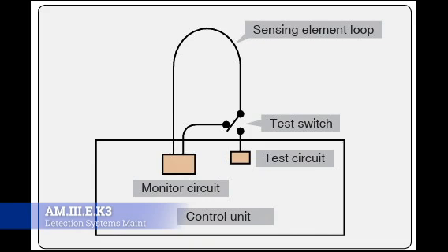Now that we understand the detection systems, what sort of maintenance can we expect to be doing on them? All right, so the most common maintenance task that will be associated with the fire detection system is simply testing it on pre-flight. There's a test circuit that you'll get up on there if you're the one doing the avionics pre-flight. You'll go through there, hit a test button, and you'll see all the lights come on. Nowadays, they'll have on the MFDs a fire detection system test that you'll run.